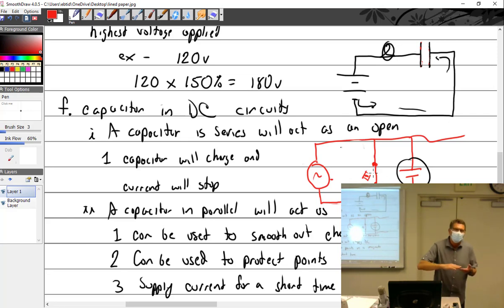By that I mean the switch starts to open, but the electrons have so much voltage that they're just jumping across the switch. And so the switch is like open, open, open, the whole time just sparking across. And finally I get to here and it's like, okay, now it can't jump anymore. You follow what I'm saying? I want it, the very second that I just barely break them apart, to be off right now, and it's critical in the magneto that that happens.